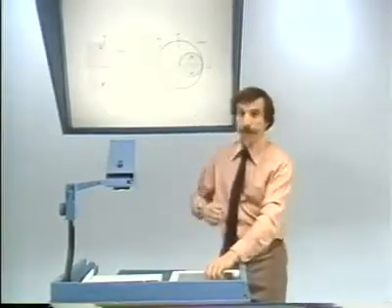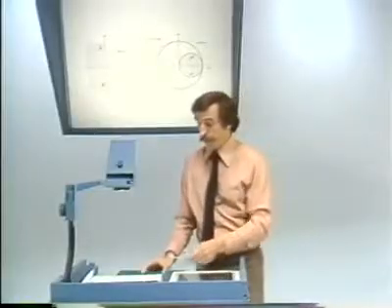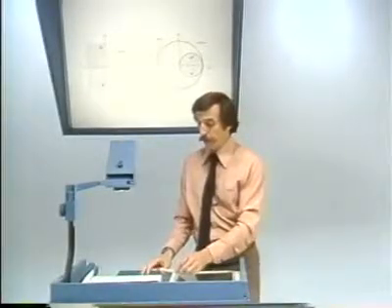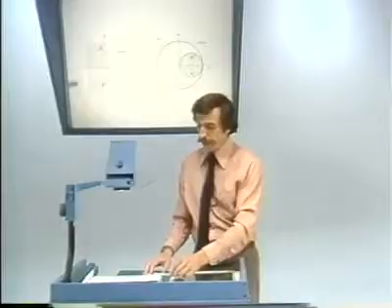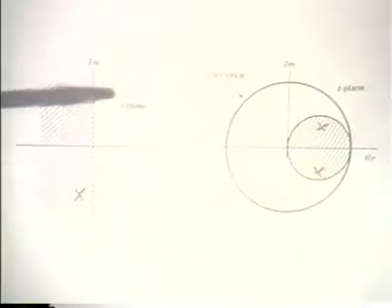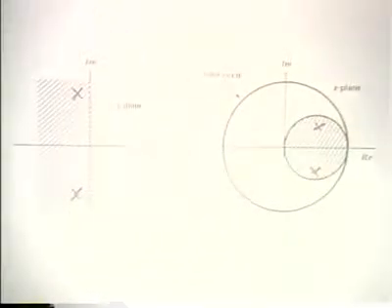Now, one plus with this method, and it's about the only one, is the fact that the left half of the S-plane maps inside the unit circle, in fact, inside a circle inside the unit circle, and so stability is always guaranteed.